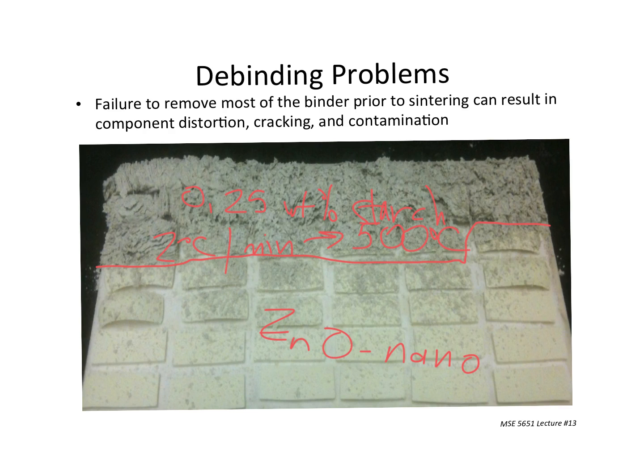What happened here is that this relatively small amount of starch at a reasonably slow heating rate, part of this is driven by the fact that this is nanoscale ZnO, so really, really tiny particles. You took that starch and dispersed it amongst some really tiny particles that have really tiny pores. Think about Knudsen diffusion and how slow that is. So rather than just sit there and make nice rectangles like we got here at the bottom, they all blew up. It's like the pages of a book. It kind of blew up in layers.